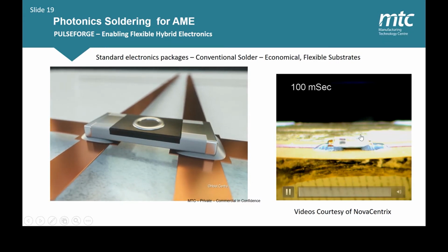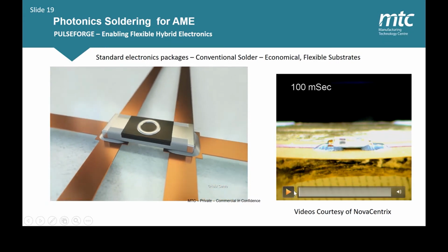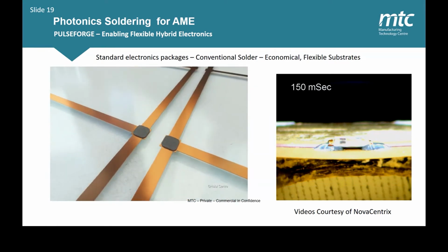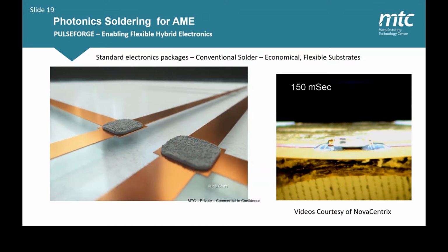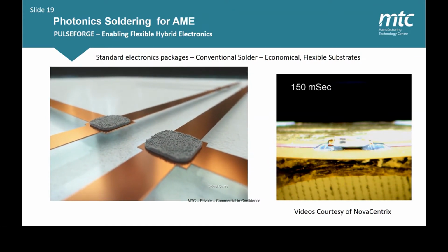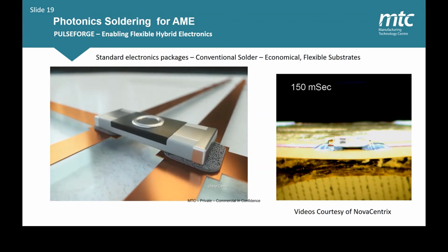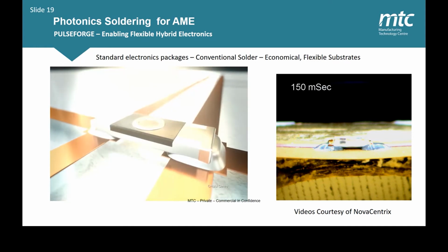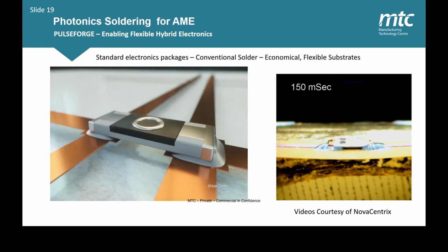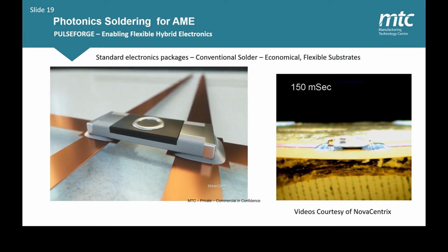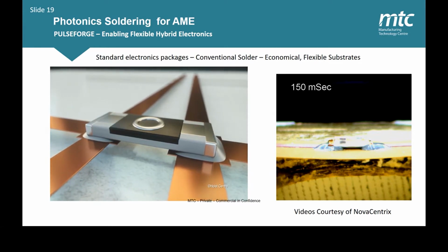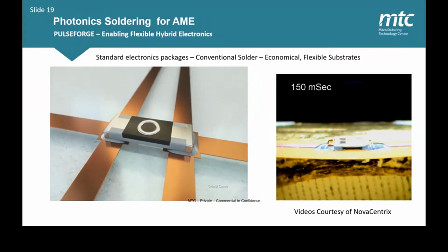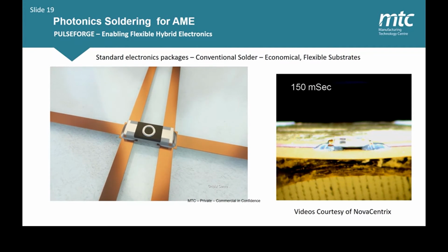The whole process takes less than a few seconds, and both heating up and cooling down is pretty much instantaneous. One thing to note here is that the substrate underneath is transparent in this animation. This is to showcase that this sort of process is applicable to even unthinkable materials such as low-cost plastics like PET, PEN, or polycarbonate. They have also been able to achieve solder reflow and really good solder joints on FR4 or even metal substrates.